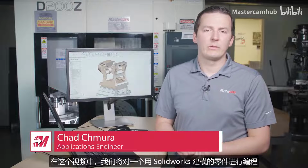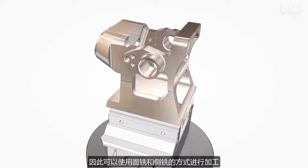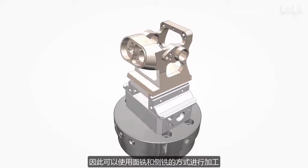Hi, I'm Chad with Mastercam, and in this video we'll be working with a part that was modeled in SolidWorks. It's based on an optical mount that's used in military applications. Since there are no curved faces on this part that will require surface machining operations, this part can be cut with flank and face milling from start to finish.